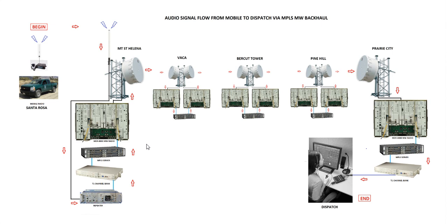And we will eventually have our entire state hooked up in this fashion, except when the final job is done, the radios here will be Ethernet ready, and we will not require the T1 channel banks to be involved at all. So we'll go straight Ethernet from the radio into the server all the way over into an Ethernet ready console, and we will only have a small chunk that's analog.